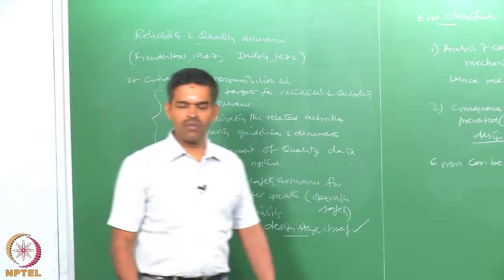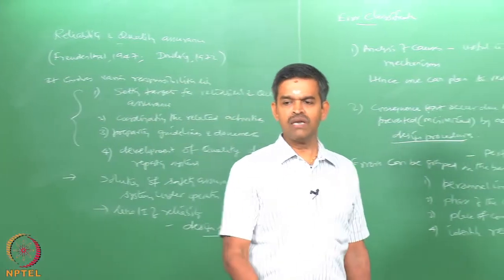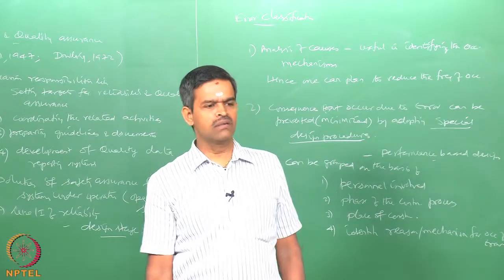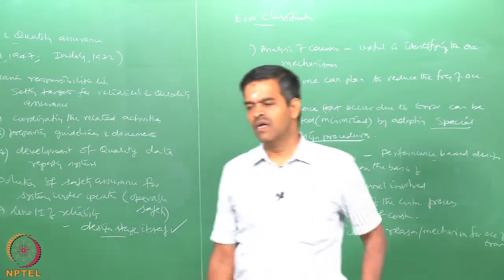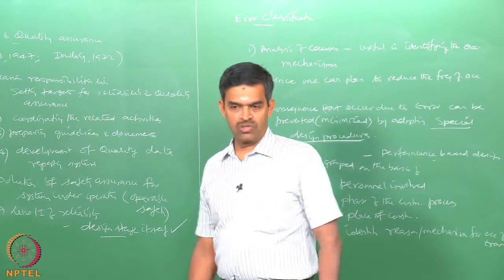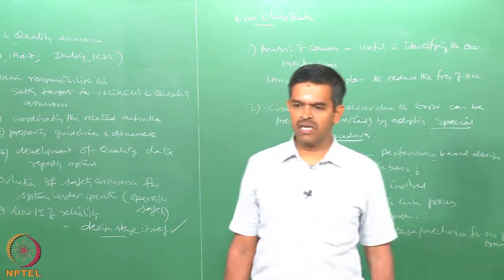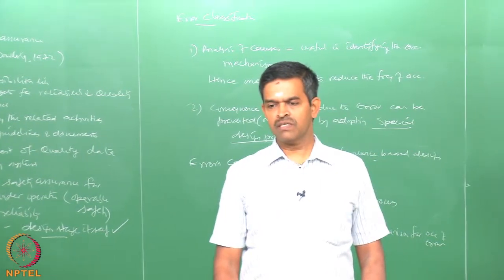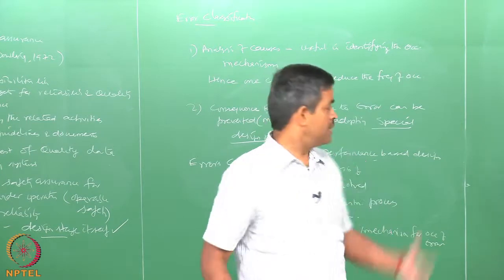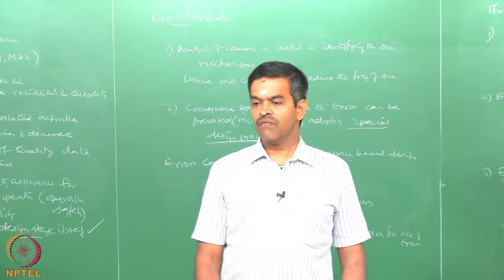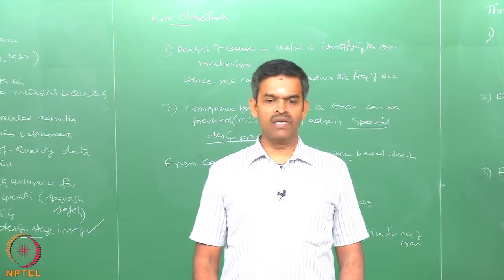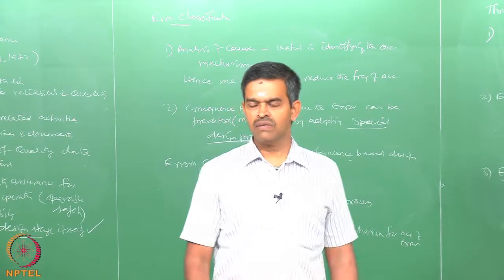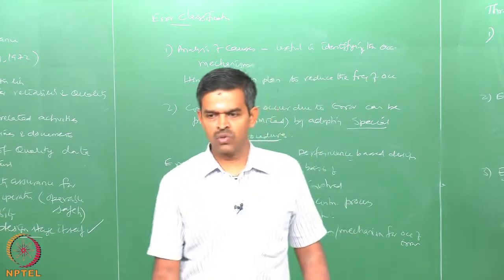So, in the next lecture we will talk about what those uncertainties are which are inherently present in the design, how they can be handled or how they are handled as suggested by various researchers, and what different tools, methods or theories can be used, so that the whole goal is to minimize errors which essentially arise, intentionally or unintentionally, from the uncertainties present in the variables R and Q, where R refers to the resistance of the system and Q refers to the load effects or the loads acting on the system.